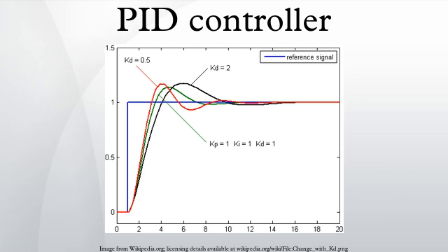Basing proportional action on PV. Most commercial control systems offer the option of also basing the proportional action on PV. This means that only the integral action responds to changes in SP. The modification to the algorithm does not affect the way the controller responds to process disturbances. The change to proportional action on PV eliminates the instant and possibly very large change in output on a fast change in SP. Depending on the process and tuning, this may be beneficial to the response to a SP step. King describes an effective chart-based method.